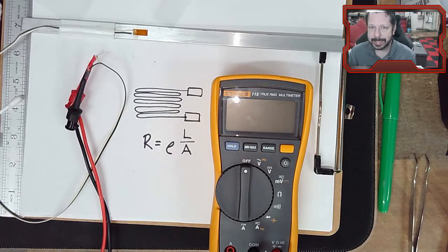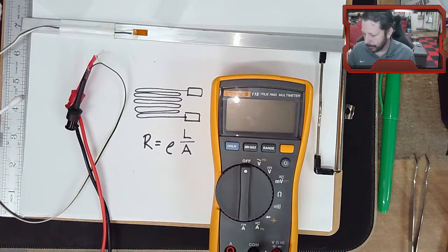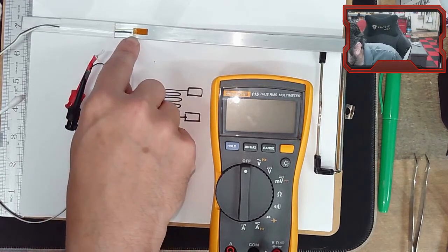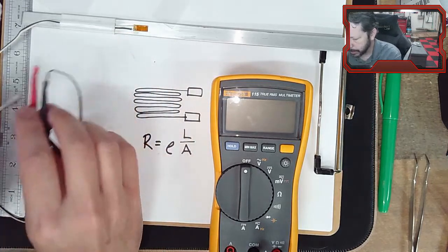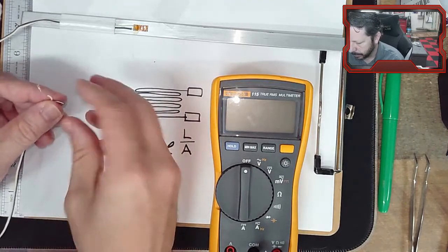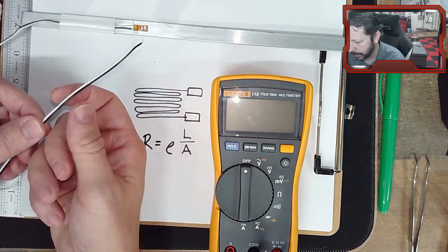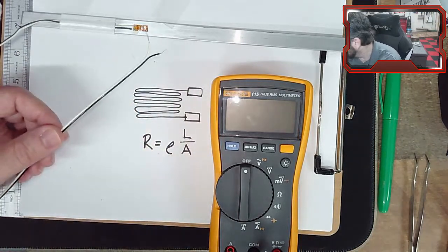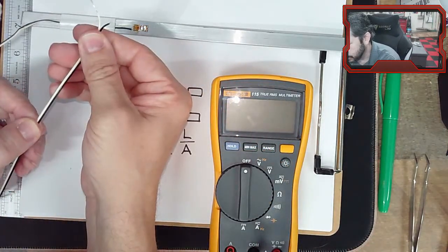There is a little bit more with the t-test. Oh, wow, you said that your strain gauge already has 2-inch leads that solder to it. Wow, that's way simpler. And it also says that you attach 3 wires. So sometimes you put 2 wires on one of these. That's okay, because there are some 3-wire strain gauge setups where it's expecting to have 3 wires on the other end. So if you have a strain gauge wire set, a lot of times that wire set will have 3 instead of just 2. I made this out of just ribbon cable wire, so I only used the 2.